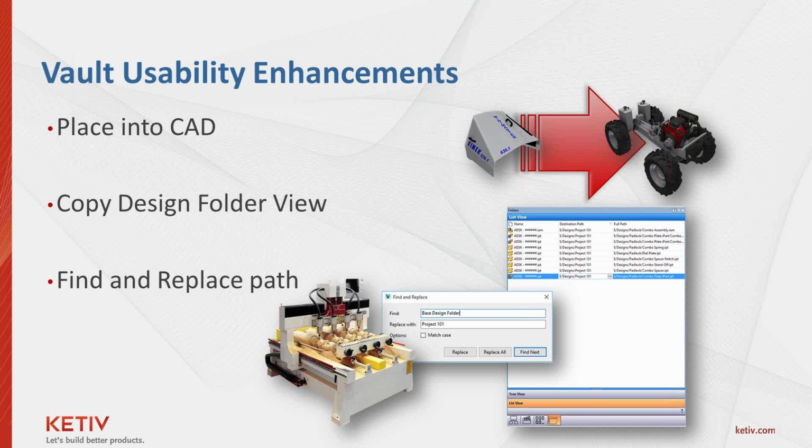And for those of you using Vault, I thought I'd throw some of that into this as well. One of the really nice things is Autodesk is looking at how we're using the tool and trying to give us the ability to use it in our workflows. So naturally, a lot of times we're inside of Vault Explorer, and you need to basically place that file into the assembly you have open. You now have place into CAD, so that you don't have to go in Vault Explorer, then go back over to Inventor and find the file again and place it. You can do it straight from the Vault Explorer.